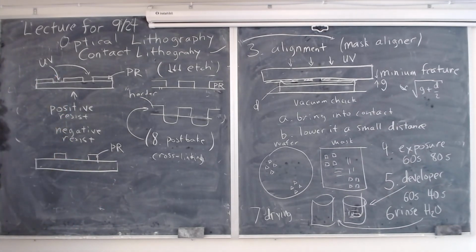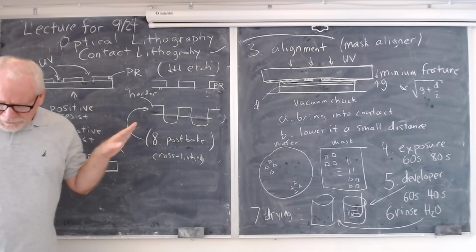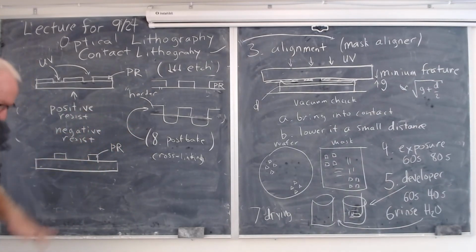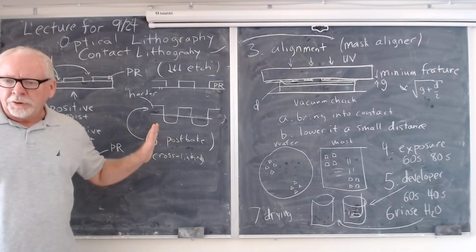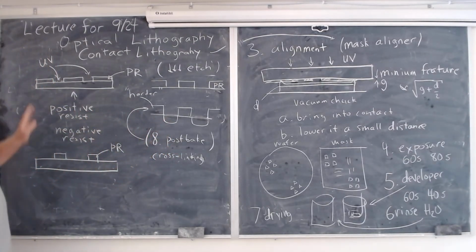Now, we've already seen that there are various reasons why you might use positive or negative resist. Negative resists tend to require more process development, and so they are used less frequently for that reason. Positive resist makes more sense to you, right? There are two things, though, where because of your process, you might use one or the other.